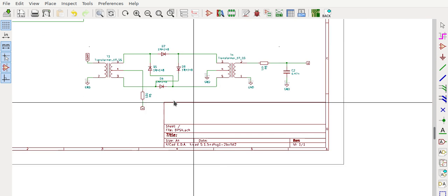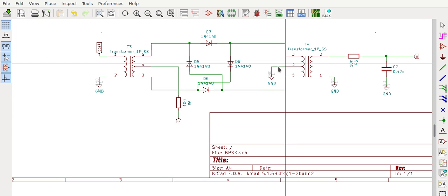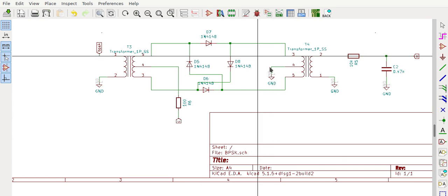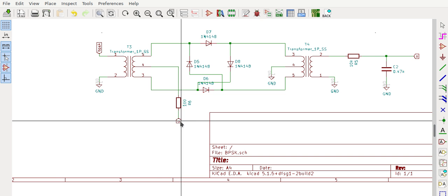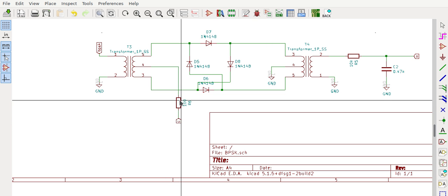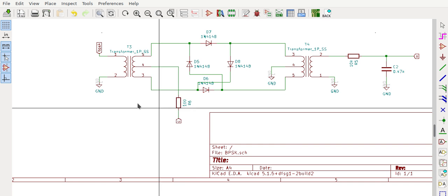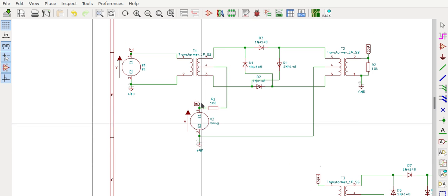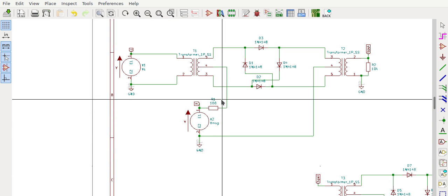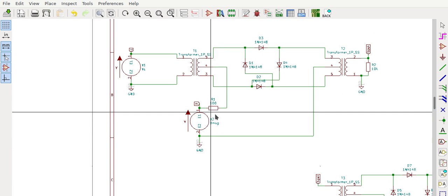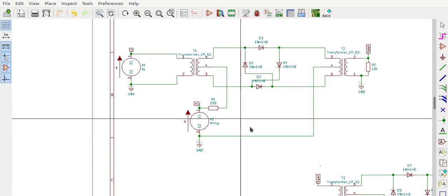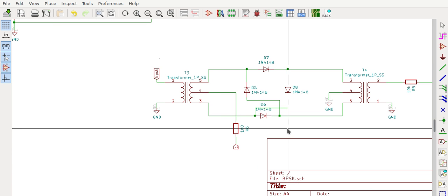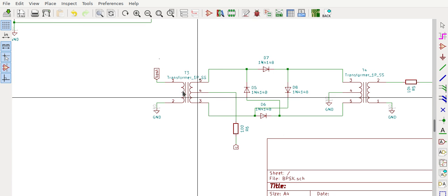In the same way, one point of the transformer, or one point of the balanced modulator, is connected to ground, and the other point is connected to label C, and then a current limiting resistor, just as we did in this case. A signal source is connected between ground and the current limiting resistor. So the exact same topology we are using here also, and then